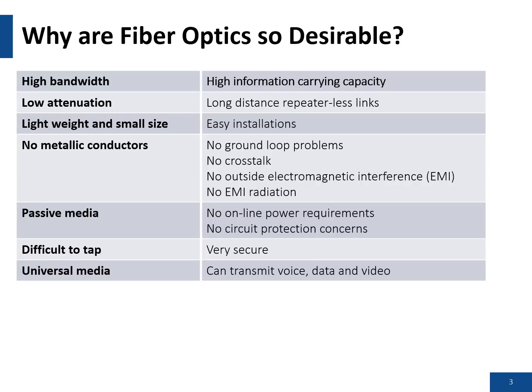First of all, it has high bandwidth, high capability of carrying lots of information. It has low attenuation or low loss, which means long distance between regeneration points. It's light in weight, small in size, and it makes it easy for installation crews to handle and to install.